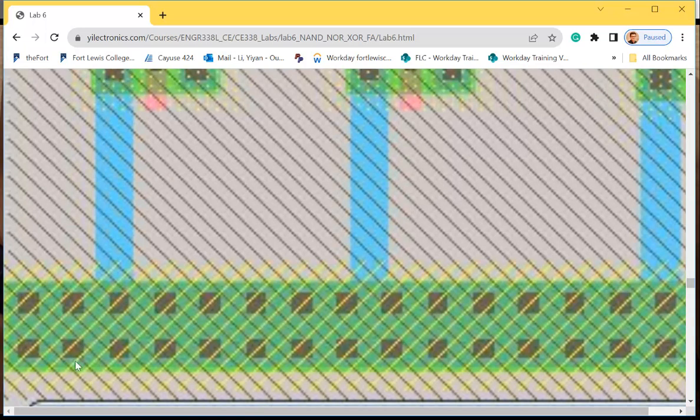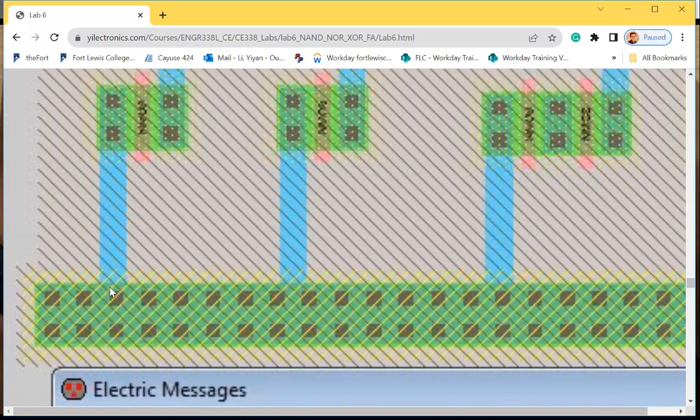I think that's why the color here looks more light green and this is more dark green because it already has a metal 1 on it. So when you are introducing a wire of metal 1 and connect the two here, the whole thing has a metal 1 already. So directly make the connection easily.